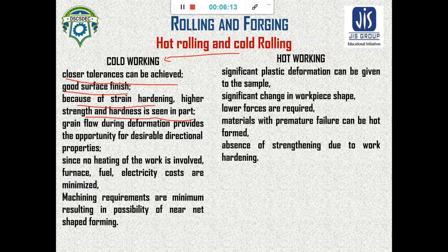Next is the grain flow during the deformation. Grain flow during the deformation provides the opportunity for desirable directional properties. That means when the material is deformed at low temperature, there is grain flow. The microstructure inside the material is compressed, and that compressed microstructure increases desirable directional properties.